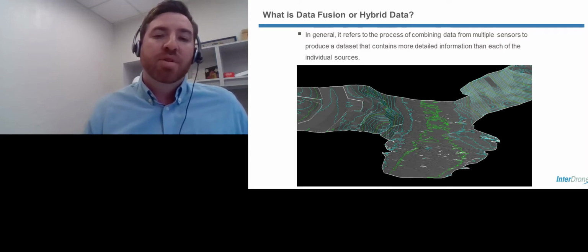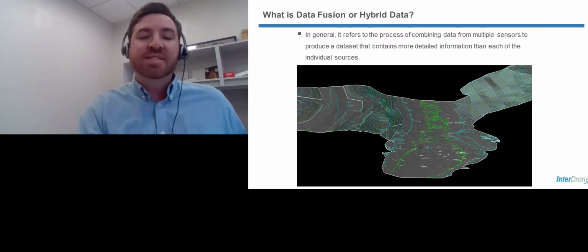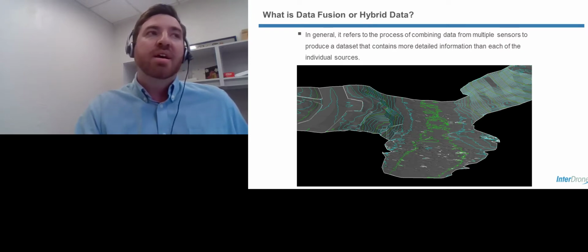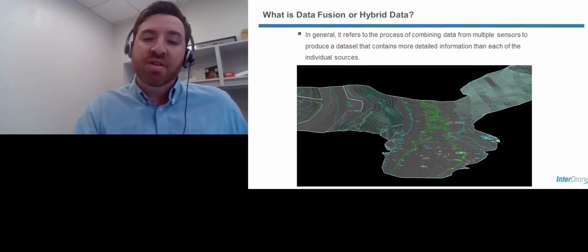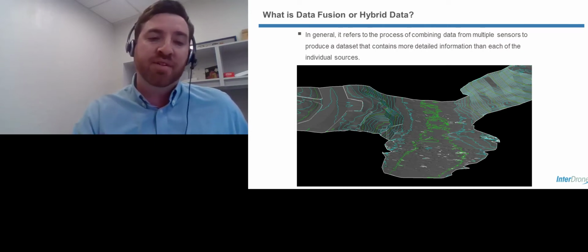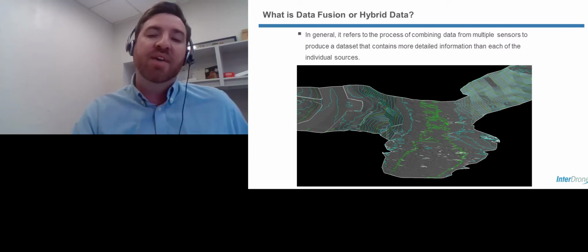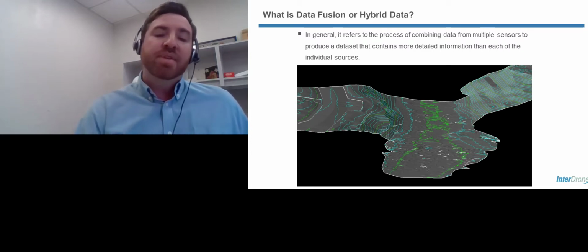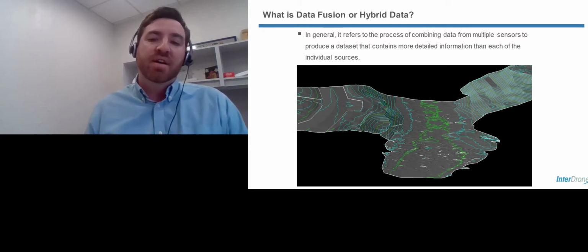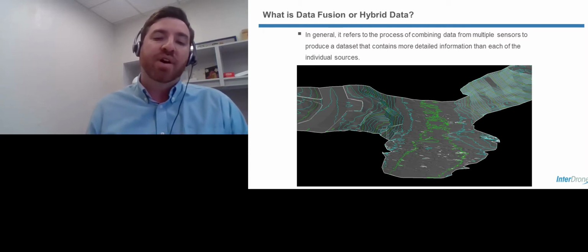we believe that mobile LiDAR is going to bring us the level of detail that we want on a road, and it's also going to, say, capture underneath a bridge and things like that. But we know it isn't going to get underneath the water. So in this example you're seeing here, we brought in bathymetric information that I'll talk to you about. And then also we incorporated drone LiDAR because of vegetation and how offset some of these areas were from a drivable area.